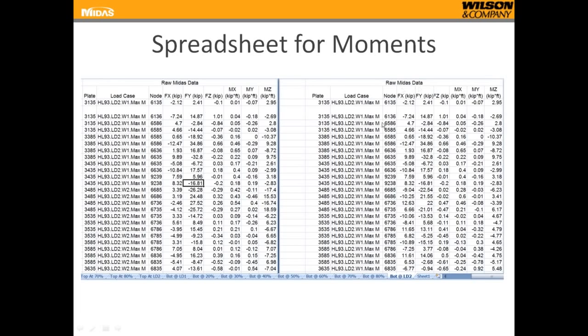I guess before I go to that, there would actually be 4 of these, since this is for live load. The load case here is for the HL93 truck at lifting diaphragm 2, with the truck placed to maximize moment in web 1. There was a different truck location to maximize moment for web 2, so those results were copied over here, also for web 3 and web 4.